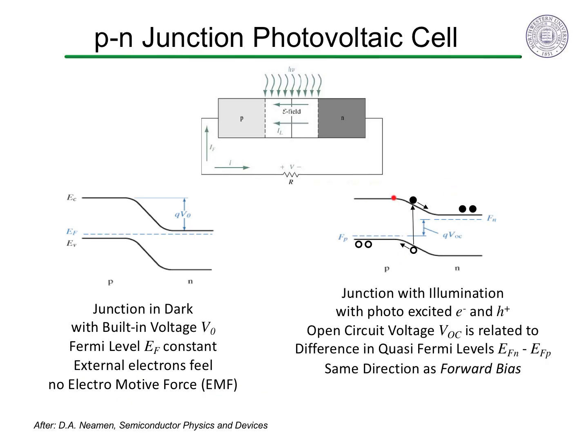When the junction is illuminated, electrons and holes are created and flow towards opposite ends. If these excess electrons and holes are not removed, the buildup of charge will induce a potential difference, driving newly created charges back, even after they thermalize. The direction of this voltage in the diode is the same as that for forward bias. In this non-equilibrium state, a non-equilibrium or quasi-Fermi level can be used to describe the chemical potential of the thermalized electrons at the electrodes in this diode.